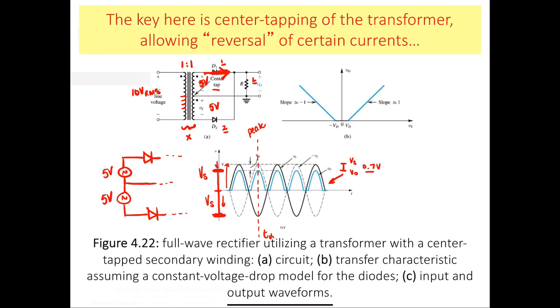So we have to step it down by this little gap, which we already know is Vd, or the 0.7 volts. So if you look at the gap from here to here is equal to 2 times Vs minus Vd, where this is 0.7 volts. So, and that peak inverse voltage is experienced at this point down here.